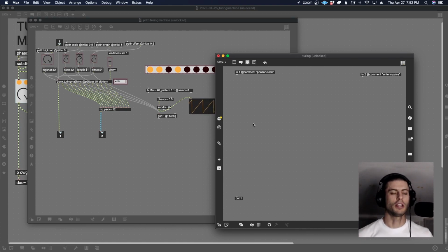The shift register is basically like a bucket brigade kind of thing, where we have, let's say, 8 slots, and a number passes into that first slot and it stores it. And when a new number comes into that slot, the one that's already in there passes on to the next slot in the row, and that process continues. As new numbers or new clock pulses come in, that first slot is getting filled with a new number, which is just a digit. It's a 0 or a 1, and it's passing it on to the next one.